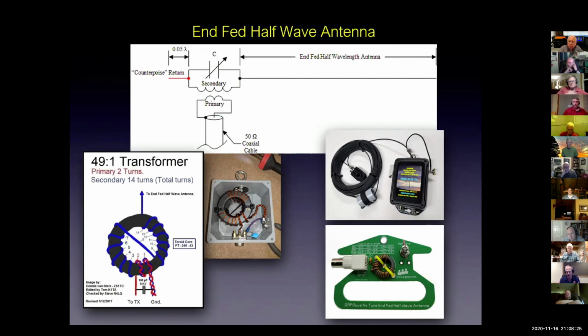I think the QRPers I'm talking to are all saying that if they have their choice and can set up correctly and get the supports, they want to run a tuned dipole, presumably a linked dipole, so they can clip in links and change frequencies. If they're just interested in getting up and getting out and being done, they tend to run an end-fed half wave or an end-fed long wire so they can tune the bands they want to work. But you need the tuner if you're going to use the long wire.